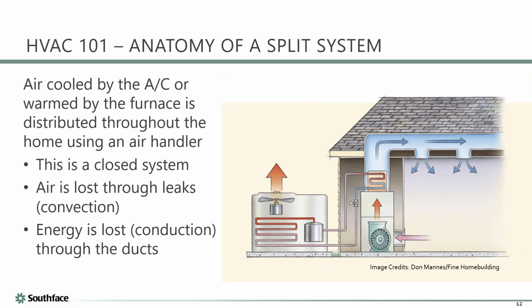It came with an ECM motor, and what it does is it runs a little ramp up and ramp down approach. So when you first start it, it doesn't just blast the air. And when it satisfies the thermostat, it doesn't just shut off. So it ramps up, ramps down, and that's like the default.